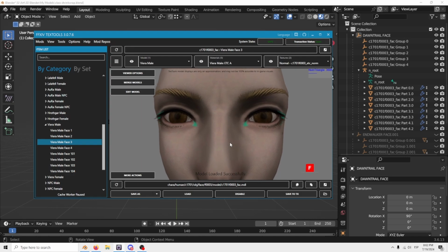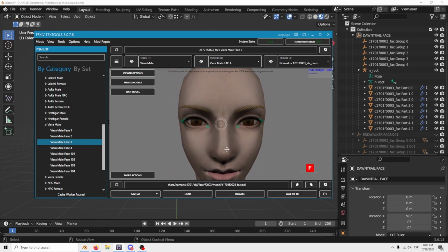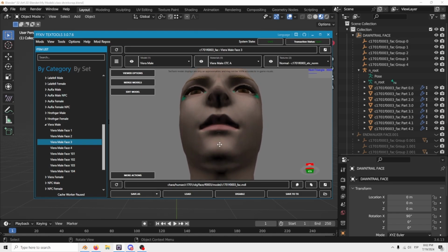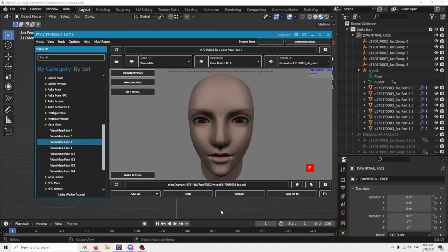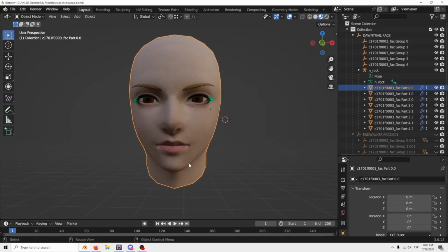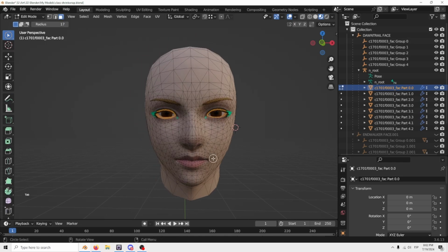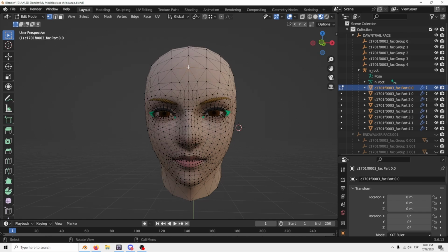Now, you might notice this is exactly what I was hoping would happen, there is a seam in the middle where the vertices join. This is a very easy fix, even if they're not visible here in Blender. Go into edit mode, select the vertex select, and we're going to, ideally with the select box, I think the select box might make it easier.